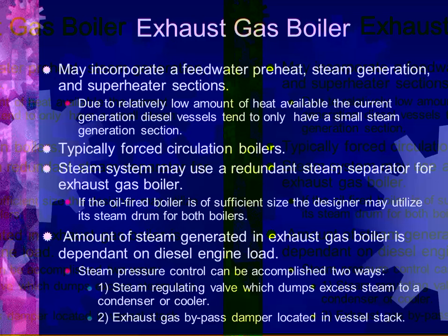And then if you're getting into bulk liquid cargo carriers, an oil carrier, tanker, if they are using steam turbine cargo pumps, you will typically utilize a water tube boiler and a similar system.